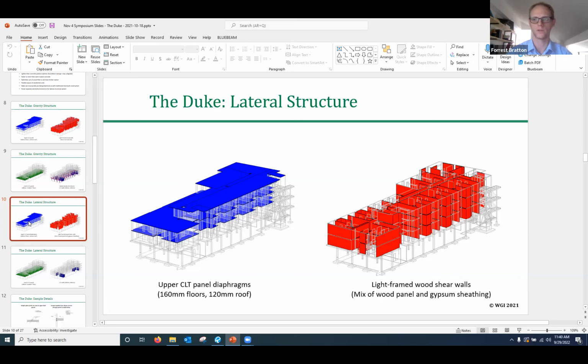In multifamily, of course, there's a lot of penetrations coming down through, and all of those had to be coordinated with structure, because every time you penetrate the panel, that's a structural penetration. So it was about working with MEP to get as many of those in a line along the span of the CLT, so we're not putting penetrations next to each other that are essentially cutting off the structure as it spans between walls. So that was one element of it.